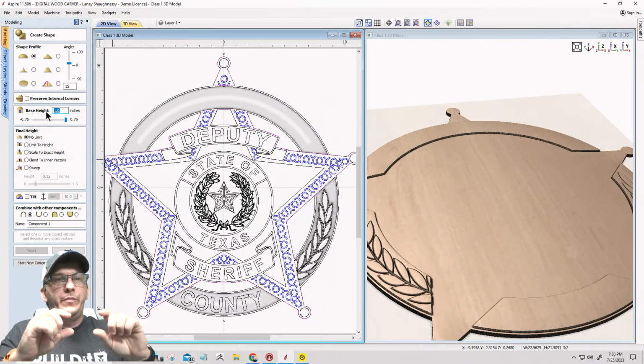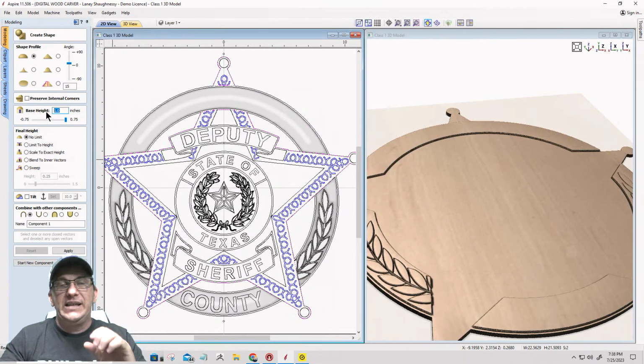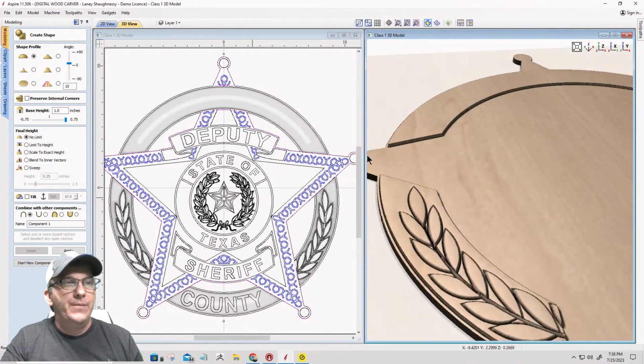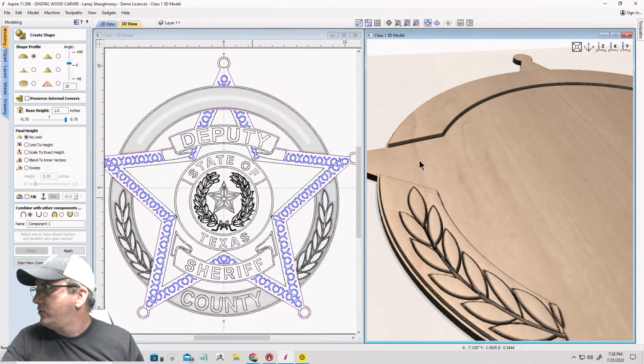of, I'm going to go 3/16. Now, why am I going to go 3/16? What is my reasoning for that? Well, my ring here is 1/8 of an inch tall. These ring parts from the bottom to the top here are 1/8 of an inch.